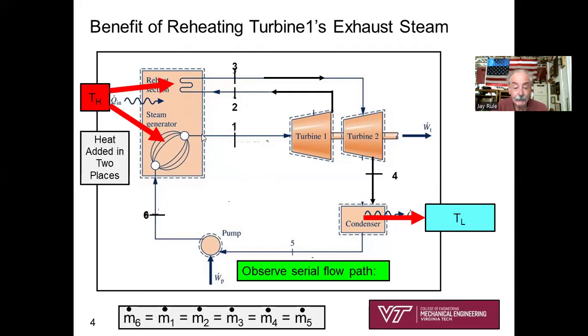Now, a little picky point, of course, is that remember, we're adding heat. I like this schematic here of the generating bank of the boiler, where the circle would represent a steam drum, but do recognize we're superheating the vapor. We're adding heat in this little section right here called the superheater section, and it's going off to the high pressure turbine, turbine 1. Okay, now we're going to get a little more complicated. It's coming out of the high pressure turbine. And I think in your homework problem, this is going to be a reversible and adiabatic turbine, I believe.